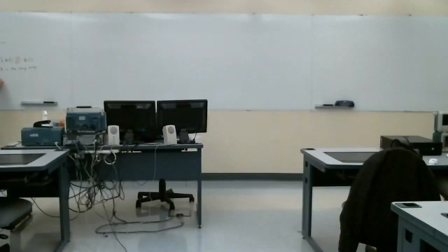Finally, the current is Vt over R, where this R is the load. It's important to realize that I won't have a current unless I have a load across those loop terminals. Right? I will always have an induced voltage, but not necessarily a current. Now, the way I've set this up, the field would be coming out of the board.